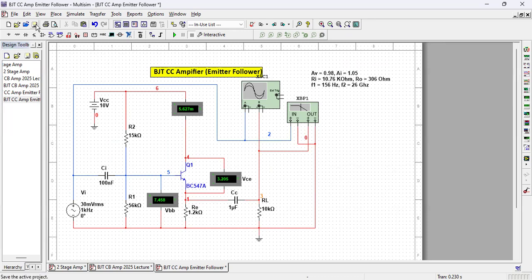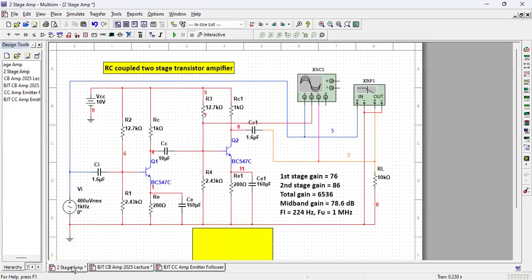Lastly, I shall show you, because in your syllabus I found there is a multi-stage amplifier model also being talked about. This is a multi-stage amplifier, RC coupled. The same amplifier is repeated here. Only these coupling capacitors are a little different, because the coupling depends on the values I showed you how to decide for coupling capacitors in theoretical classes a few lessons back.